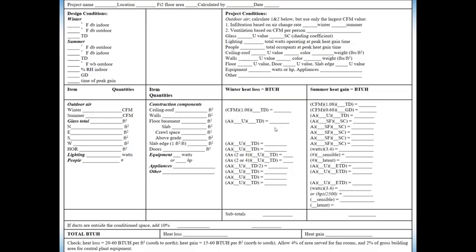It is like the quantity, peak heat loss or heat gain calculations. We are doing it, and we have the heat maps. So from heat maps we can calculate the outdoor temperatures, like the coolest temperature for the elevation that location has. And for the winter case it is this one. For the summer case there are some other numbers such as the relative humidity.